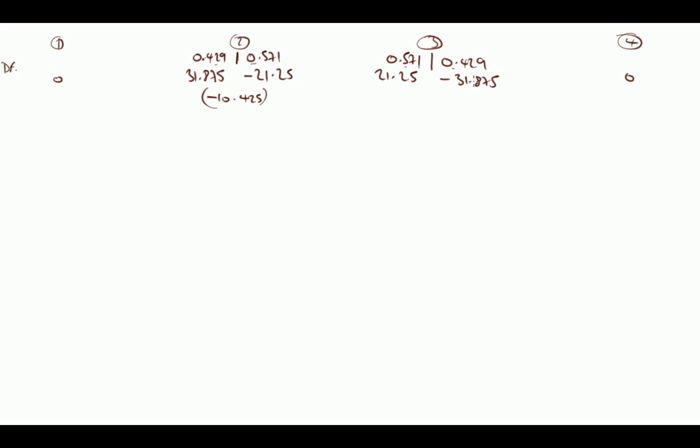We've come anti-clockwise 31.875. So we need a clockwise moment to balance. So a positive moment of, did I write that? 10.625, yeah, so that's equal and opposite. So 10.625 as a clockwise balancing moment.